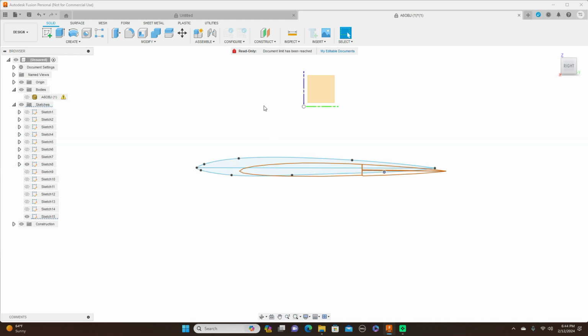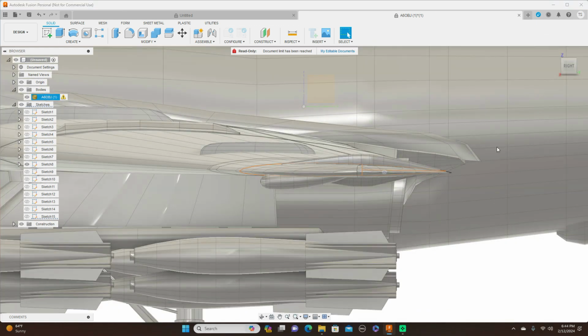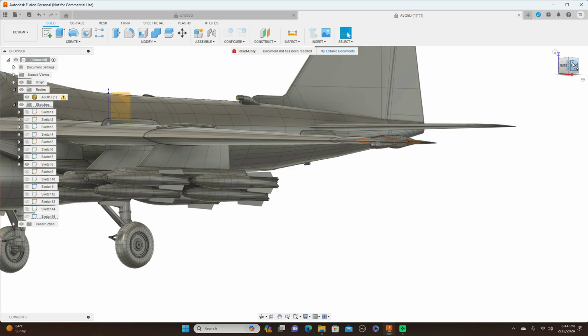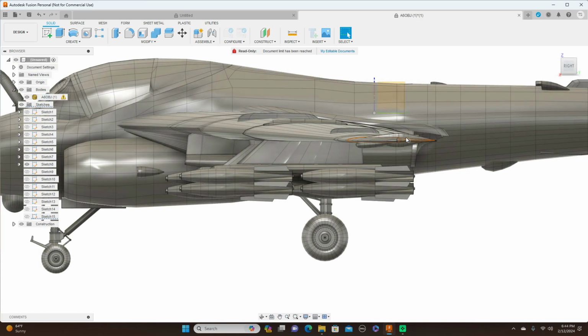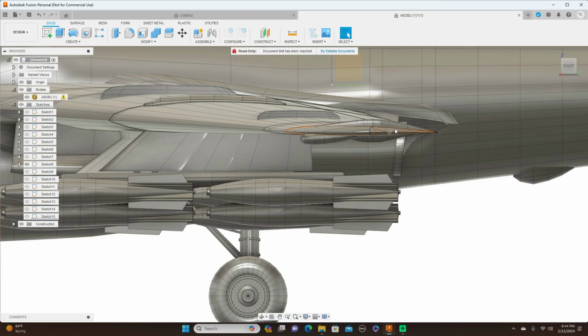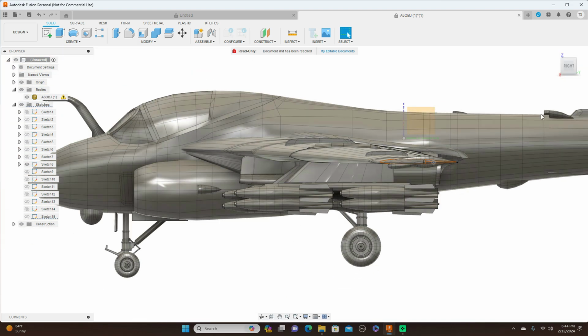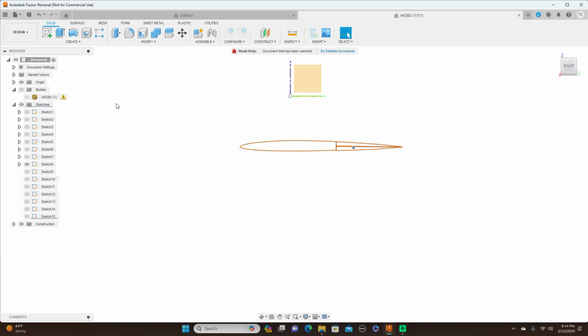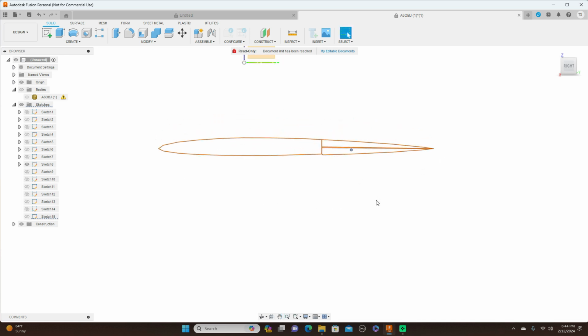Okay, we just have one more here to go. Now, when you're doing these too, let's say there's all these other parts that you have in here that'll show in your sketch, only draw or sketch on the offset plane what you want to see, or what you want on it. Like there's extra parts, erroneous things on here. If you don't want those, then don't sketch them.